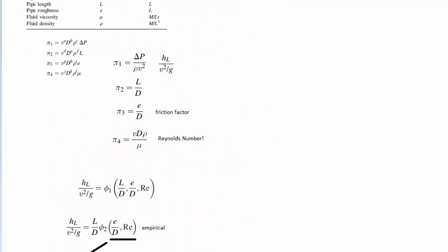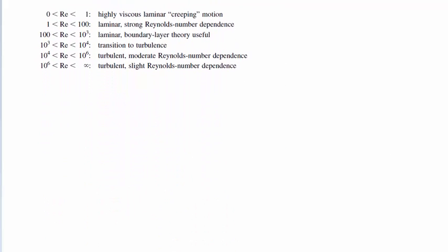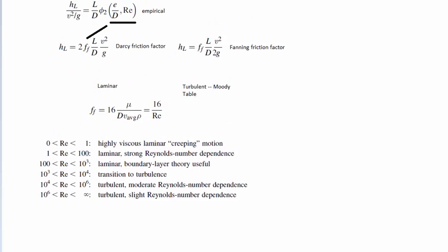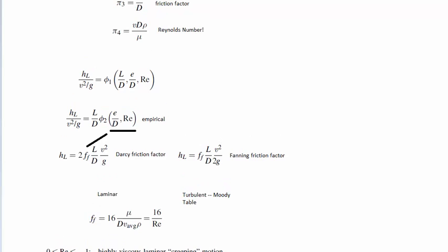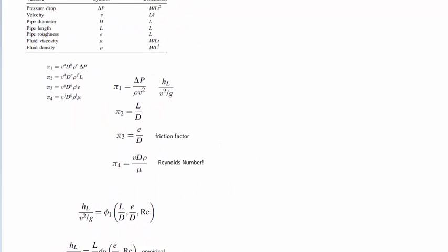Notice that the Reynolds number depends on all of these factors. So again, the reason why we nondimensionalize equations and get these dimensionless groups is because they help us characterize the system. In this case, the Reynolds number lets us tell whether or not a flow geometry is going to be laminar or turbulent.